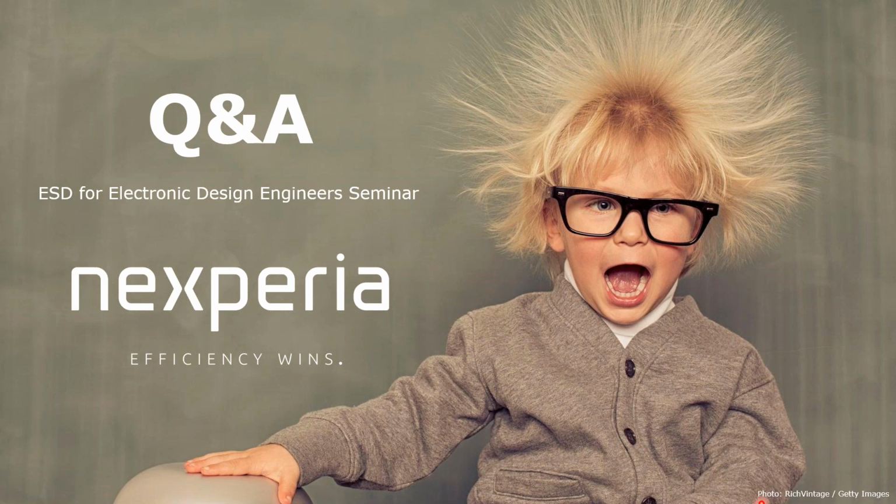Our effort is in cooperation with the ESD Association and Working Group 26. This modeling technique is called SEED, System Efficient ESD Design, and we are providing SEED models on request, which are very complex and include the complete turn-on behavior and everything you saw on the TLP slide in the model. But you should know what you are doing if you're using a model like this.